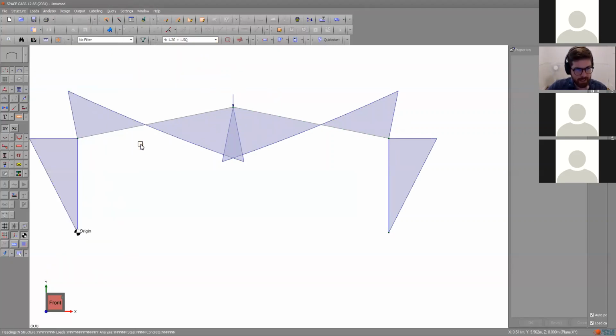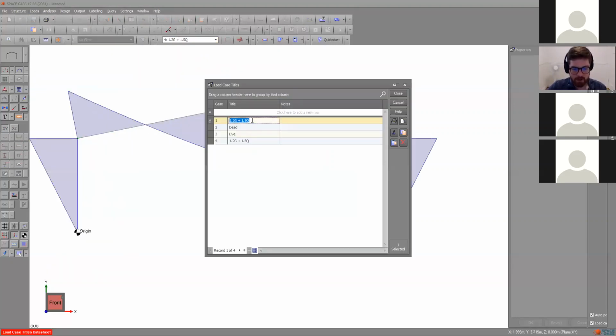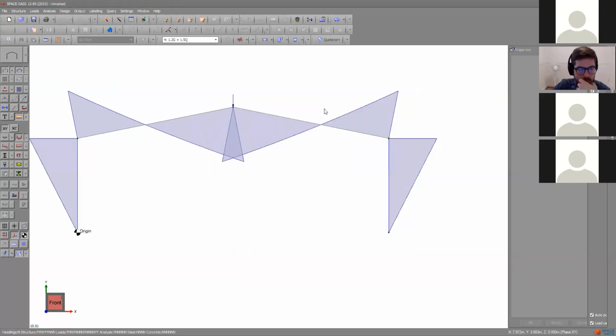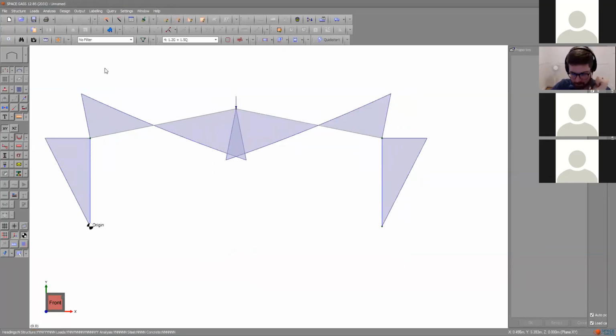You saw though, I accidentally overwrote the title for my first load case. So when you're numbering combination cases, give them a new individual load case number, so they're treated themselves like additional load cases. So if you have 3 normal loads, your combination load case should start at number 4. Loads, data sheet, local global self-weight, load case combinations.